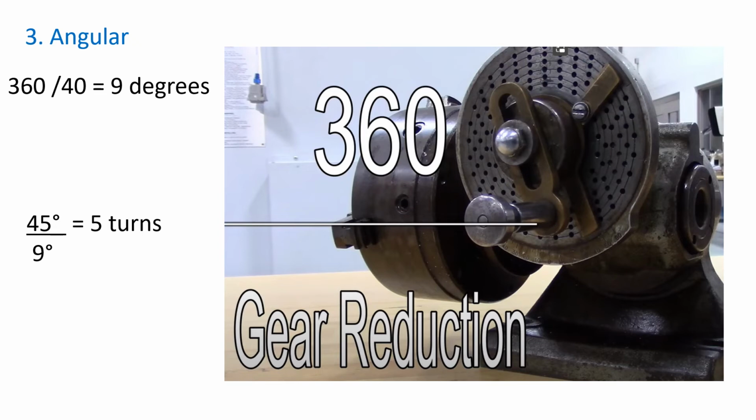Indexing takes a lot of practice, especially if you're setting up your first job. Always do a light scratch cut around all of the indexes to make sure that you haven't made an arithmetic mistake.